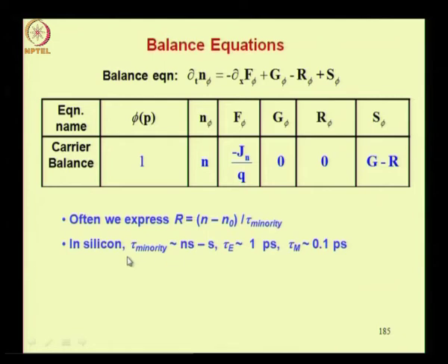Now for instance in silicon minority carrier lifetime changes from nanoseconds to seconds, that is the order. For comparison, we have also given here the energy relaxation time and momentum relaxation times, which will appear in the equations that we are going to consider shortly.